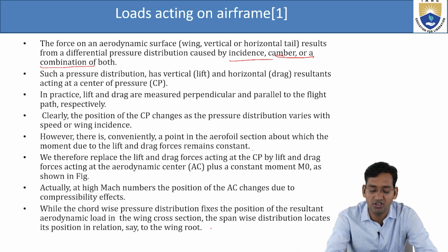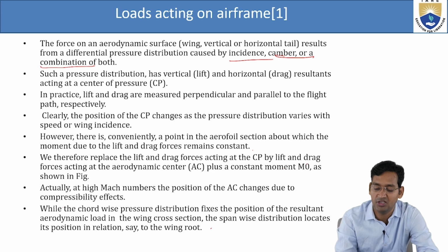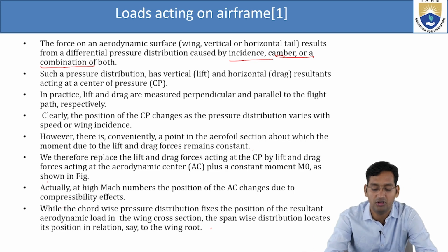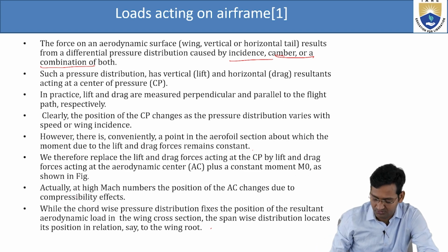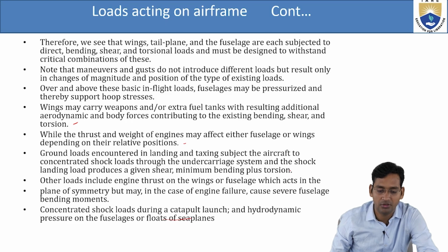We therefore replace the lift and drag forces acting on the CP by lift and drag forces acting on the aerodynamic center plus a constant moment M naught, as shown in the figure.